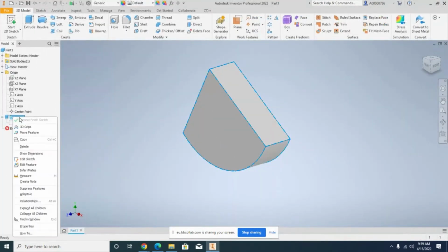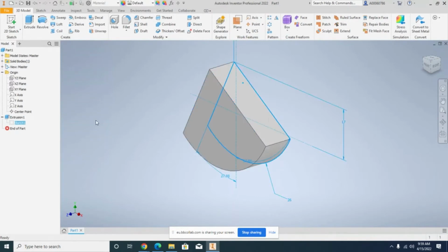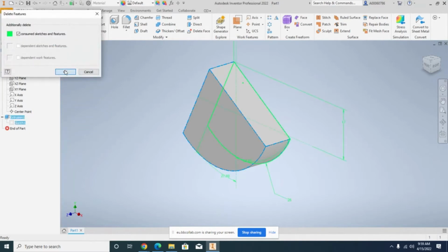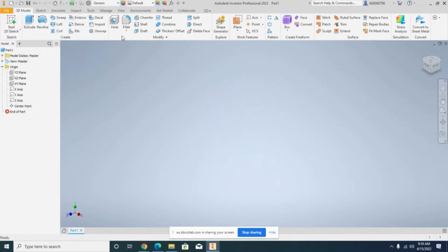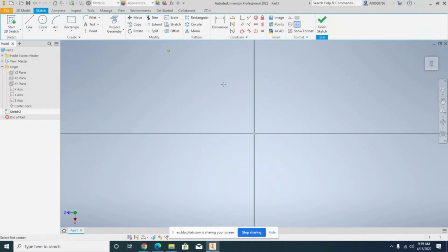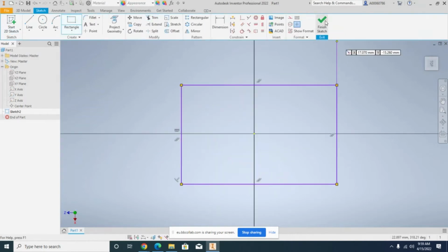When we're dealing with extrude, you notice that you have only one sketch. So one sketch, you give it a thickness or give it a height. But with loft, it's different. In loft, you have to start to do a sketch, choose this work plane. Draw as an example your rectangle.